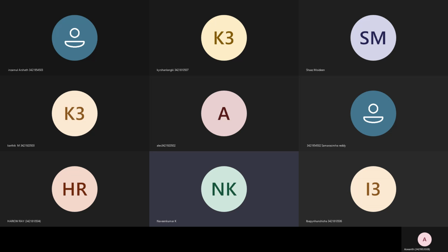Consider the cantilever retaining wall, in which case we go for the cantilever retaining wall. If you need the height in the construction site from 3 meters to 6 meters, then you have to go for the cantilever retaining wall. Considering this category, we have covered the design of the cantilever retaining wall.